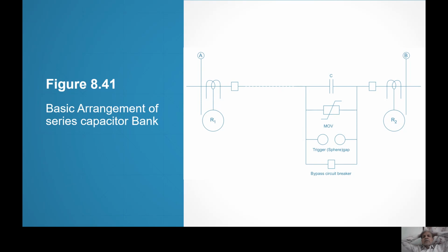If it's a high fault current, a low resistance fault, a low impedance fault, then I'm very happy, because then there is no capacitor in circuit. But unfortunately, the fault is a small double line fault at a very large distance, or particularly an LG fault, which has a very small current. Now, for the small currents, IXC will be small. So, IXC will not be fully shorted. No doubt, MOV will come in picture.